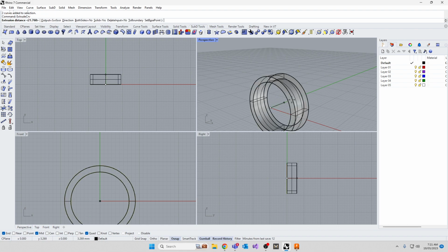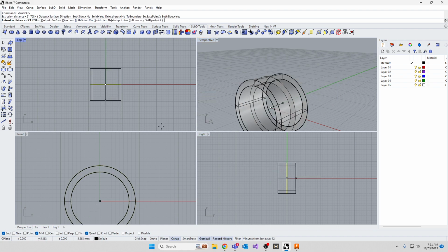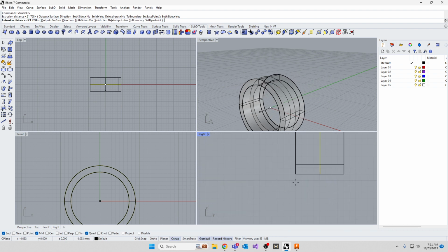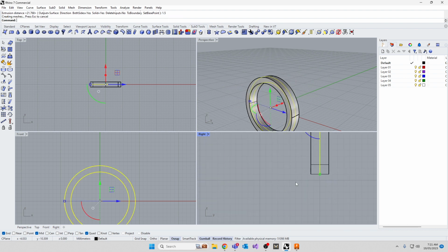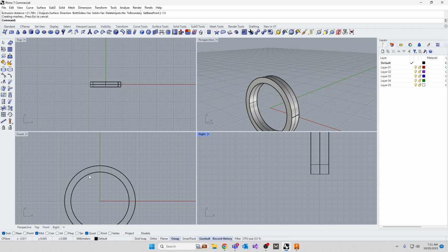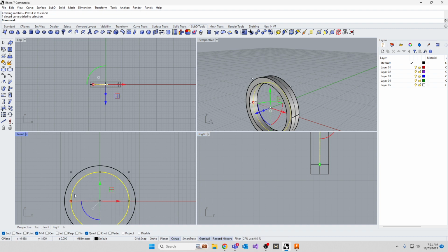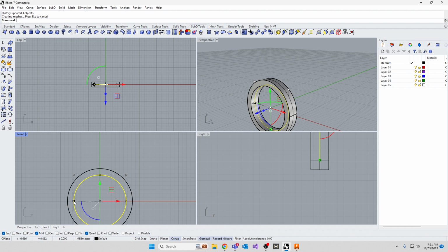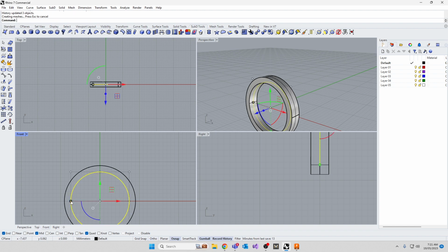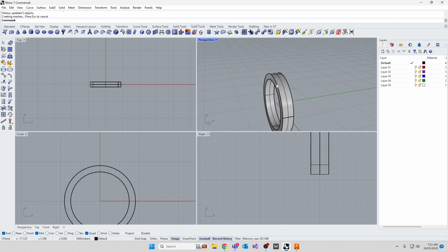So if I extrude that like I did in SolidWorks, let's go both sides, and let's draw that to, I don't know, 1.5 to make a total of 3 mil. All right. If I now change the curve, if I still got it, you might still be lucky. Yep, you can still change the whole ring. All right, but you can't see your history of which one you changed, right? Now watch what happens.